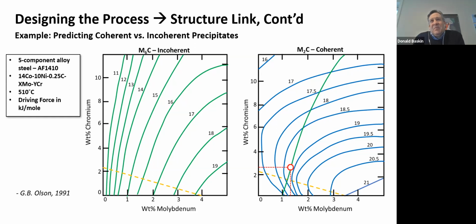It is real, but what it is when you have, let's say, you've got your bread. That's a bad example. You've got your matrix of steel, or aluminum, and you want to precipitate out these little particles. There's energy associated with that. As you heat this material up, the driving force for these little precipitates to grow out of the material increases.